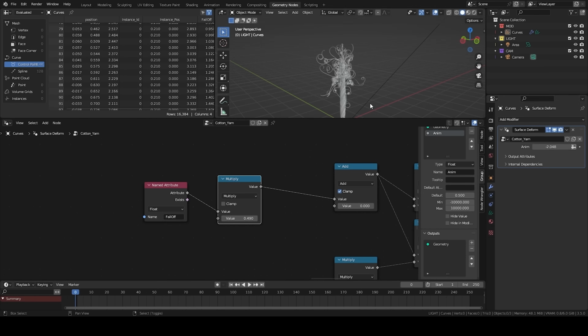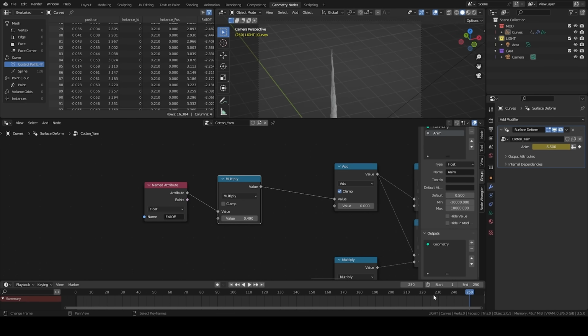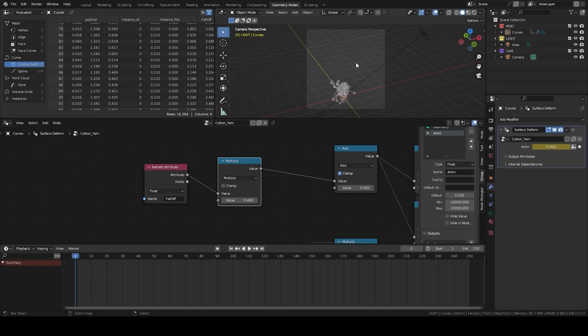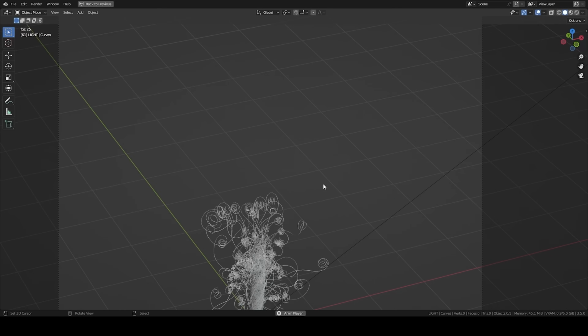And now I'm able to start putting just a little animation key, starting from now, in which at the 250th frame fully unfolds my curve at -5. And I press I on the keyboard so I can place a key. If I look now, I've got my yarn unfolding. And this in a completely procedural way and without simulation.